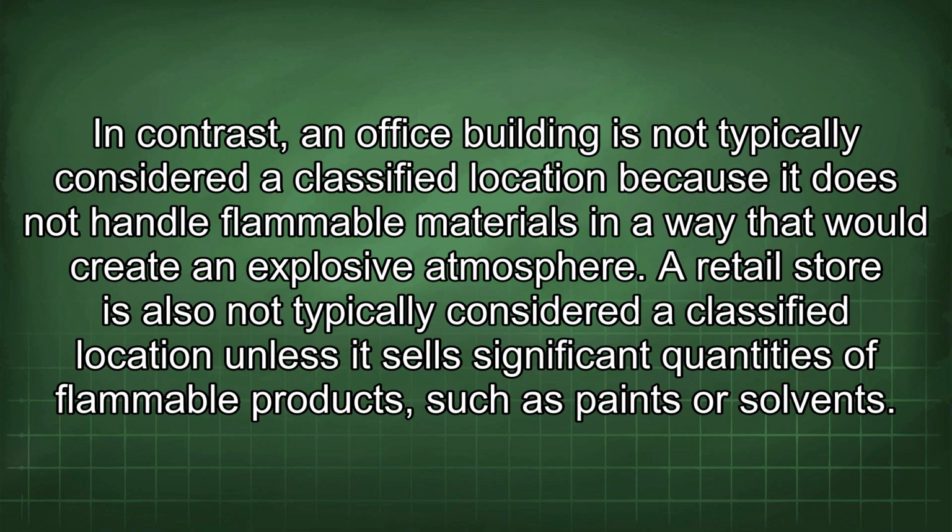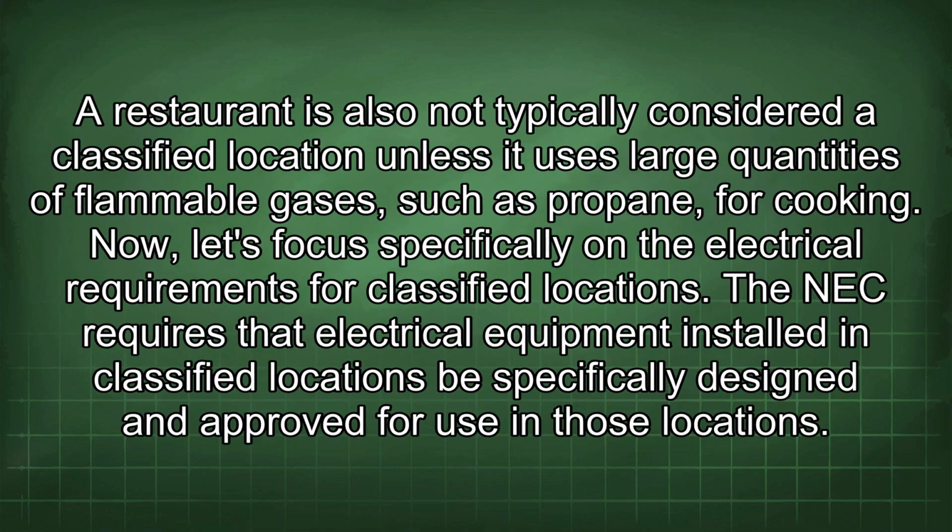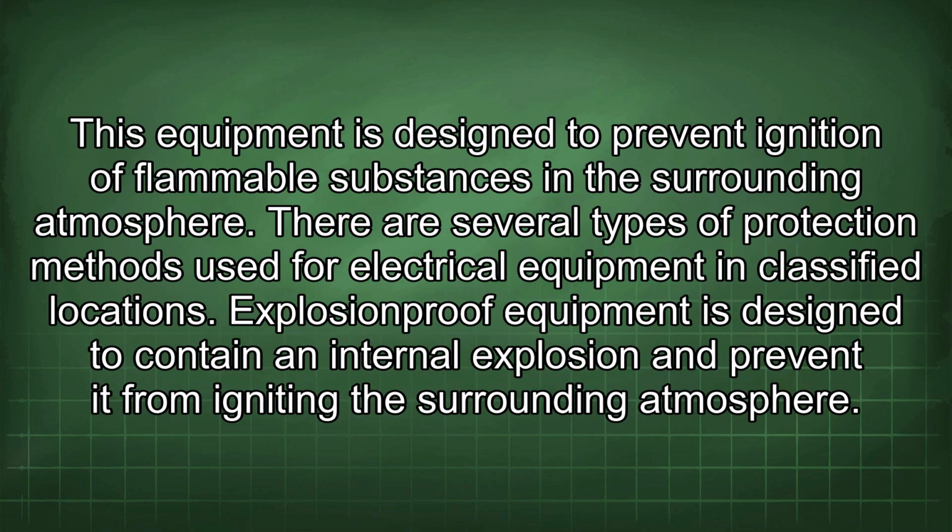A retail store is also not typically considered a classified location unless it sells significant quantities of flammable products, such as paints or solvents. A restaurant is also not typically considered a classified location unless it uses large quantities of flammable gases, such as propane, for cooking. Now, let's focus specifically on the electrical requirements for classified locations. The NEC requires that electrical equipment installed in classified locations be specifically designed and approved for use in those locations. This equipment is designed to prevent ignition of flammable substances in the surrounding atmosphere.